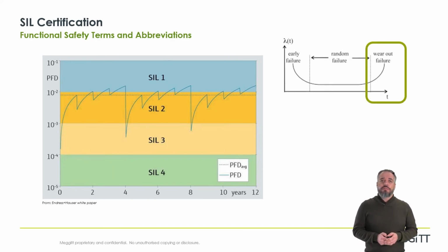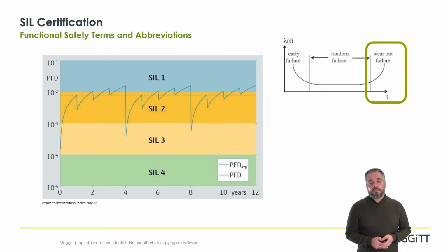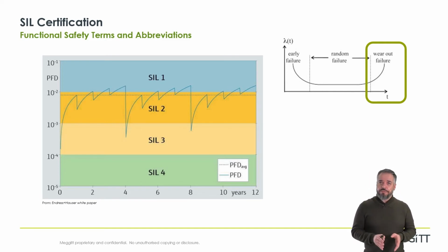As we all know, even when 100% tested, electrical and electronic components will age, and there is always a limit to the operational life that we can consider. Therefore, the standard has specific rules for cases where very high proof test coverage values are stated. The standard also takes into account the maximum mission time of a device for all PFD average calculations.